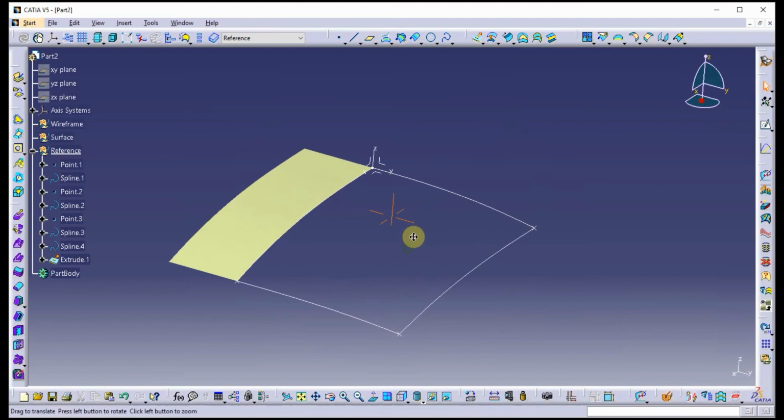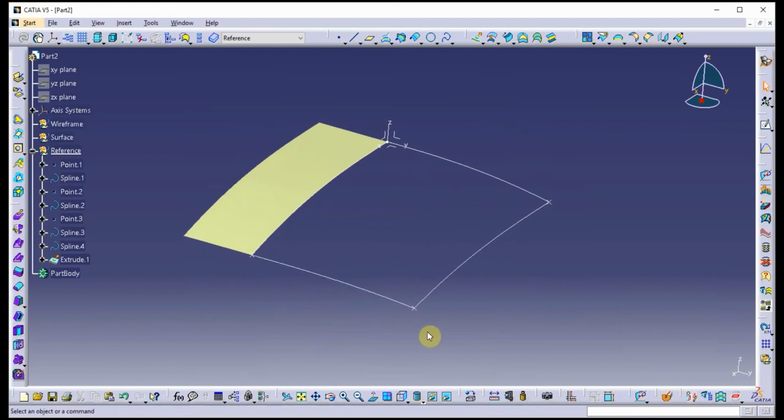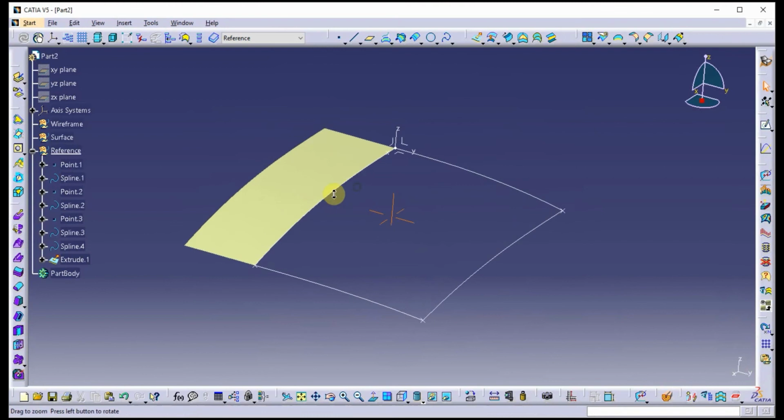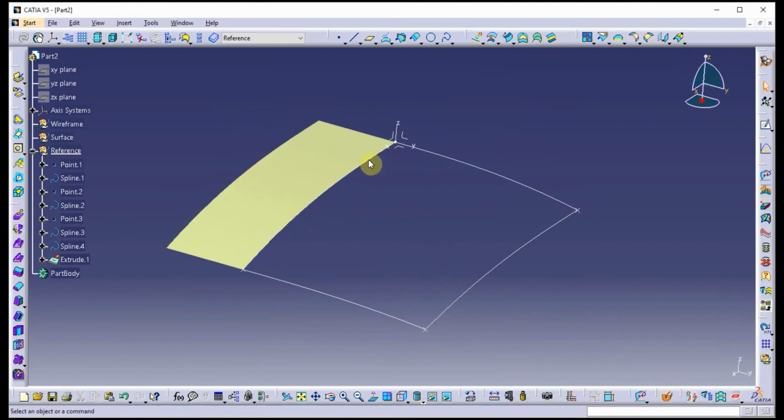Now, the other ones I don't really care about. It just depends on what the final design is going to look like. But this is the main setup I have for doing seams. I've got a seam spline, and I've got my curves that go, in this case, we want to call it normal to that seam spline. That's going to be mirrored over. So I want to make sure they have the level of continuity that I want coming into the seam. In this case, it's G2, and I have G2 coming into this, and I have my reference surface.